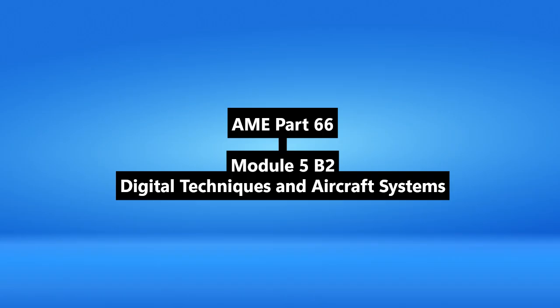It's layered. In the middle is the super thin glass or plastic the light travels down. Around that is the cladding, another optical material, but with a slightly different refractive index. Okay, that difference causes light hitting the boundary at shallow angles to reflect back into the core, total internal reflection. It keeps the light trapped inside. Then you've got buffer coatings for protection, strength members maybe made of Kevlar, and an outer jacket for overall toughness. So there. And the light source and detector.